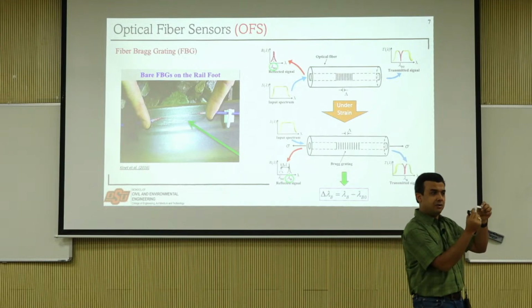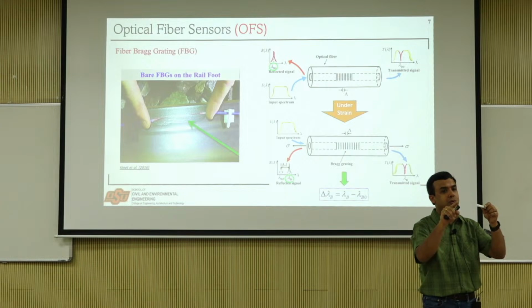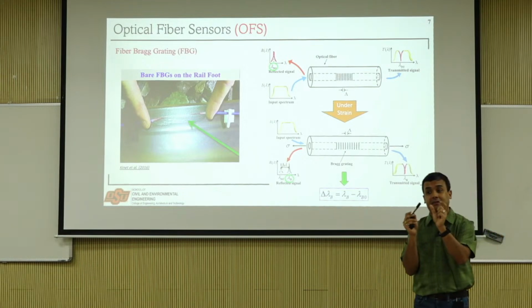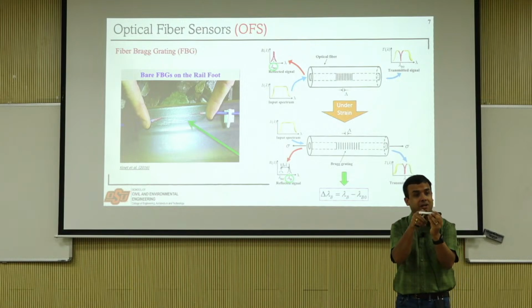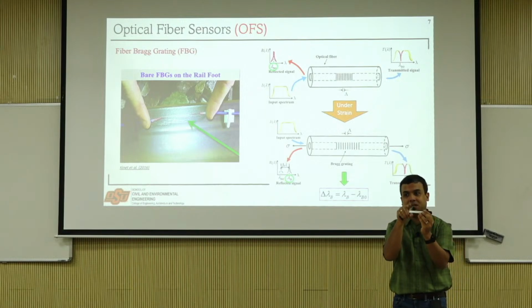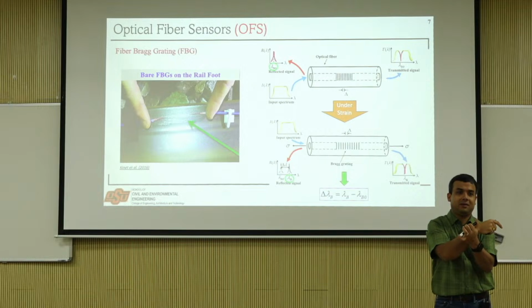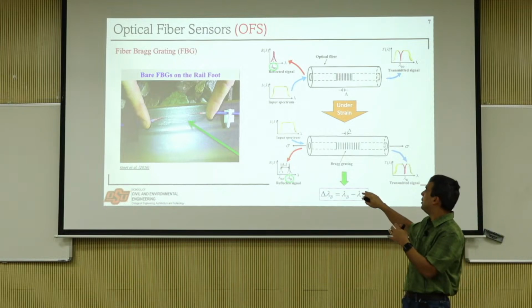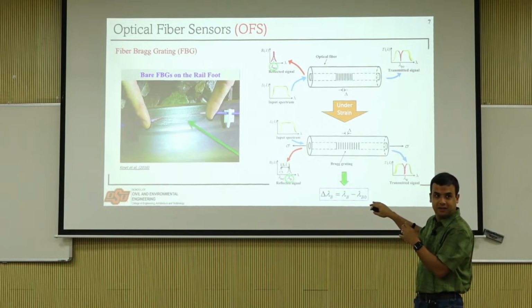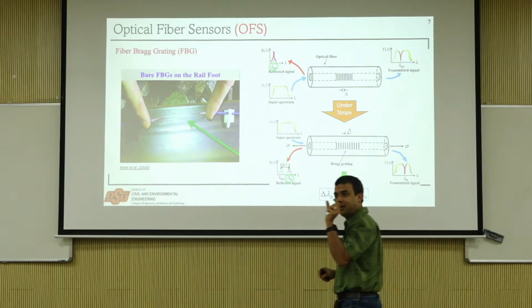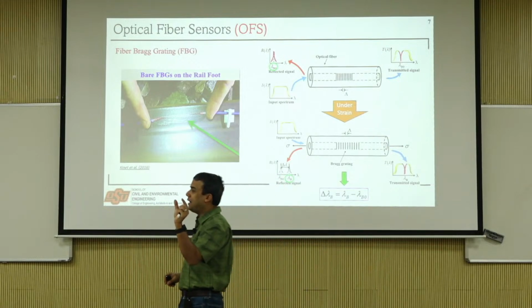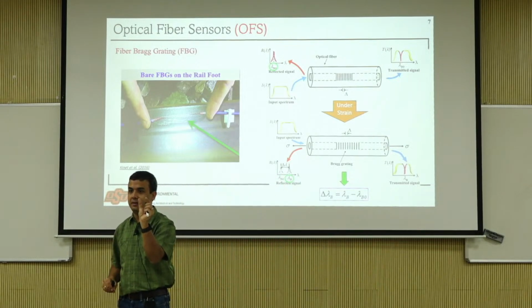When it is transmitting through, if there is some etching, there is going to be some wavelength that interferes destructively with that etching distance, and that wavelength is going to get reflected back. The remainder will go through. You can actually track what wavelength is being reflected back.